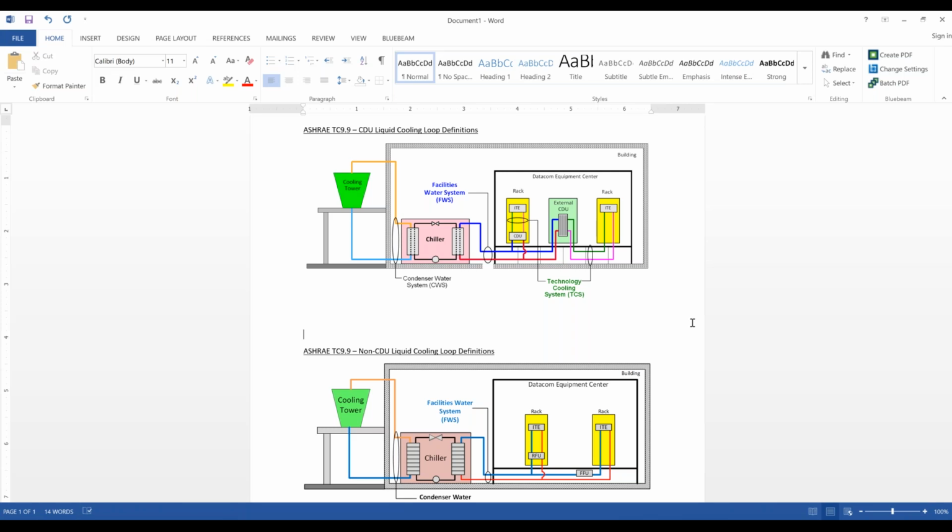I totally agree that the FWS should be harmonized, because in most applications, we're not just going to have one system in a data hall or at least in a data center building. We're going to want to have multiple systems, and we're not going to want separate FWSs for, say, a cold plate versus an immersion cooling system versus a rear door. In fact, they may be integrated, where the rear door effluent becomes the input or the supply to the cold plate technology. So yeah, I agree that on the FWS side, it needs to be harmonized, but on the rack side, I question that.